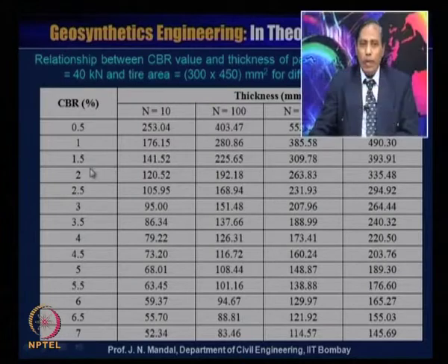For any value of the CBR and for the number of passes, you can directly determine what should be the thickness of the pavement from this table.